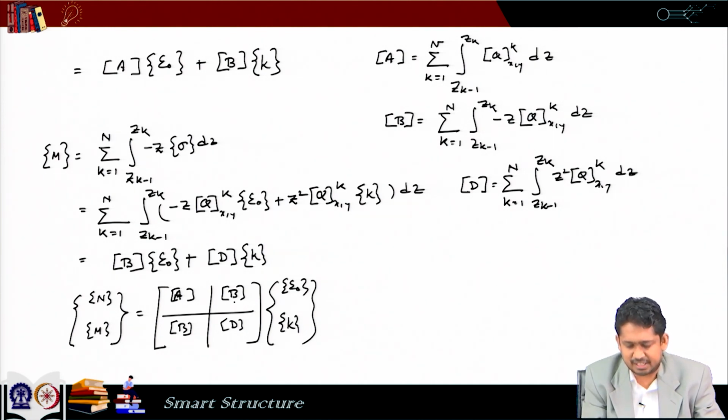So, this B matrix signifies that even if there is no in plane displacement component, suppose in plane displacement component is 0, even then just out of plane displacement components, because of this coupling, can give rise to something n. Or in other words, if I apply pure in plane load, then also some kappa which contains out of plane displacement can be induced.